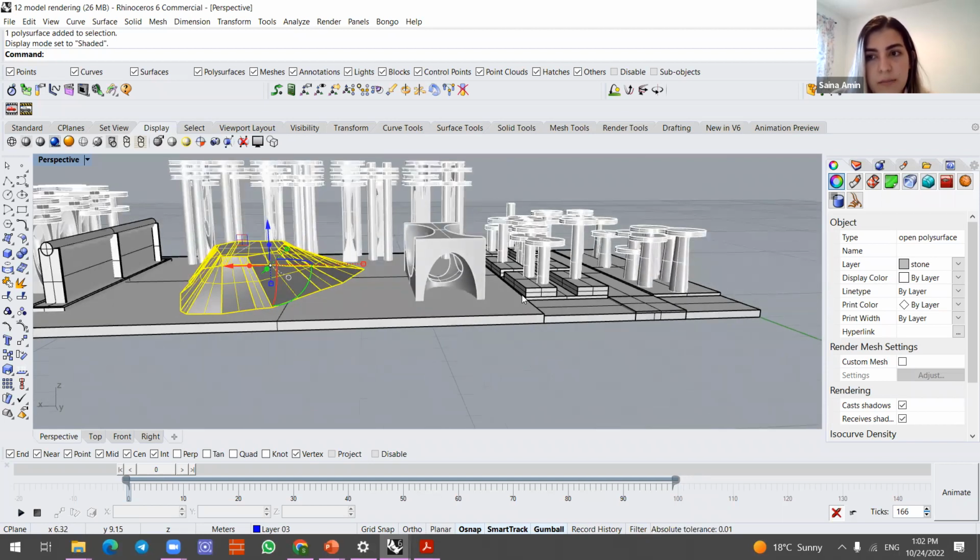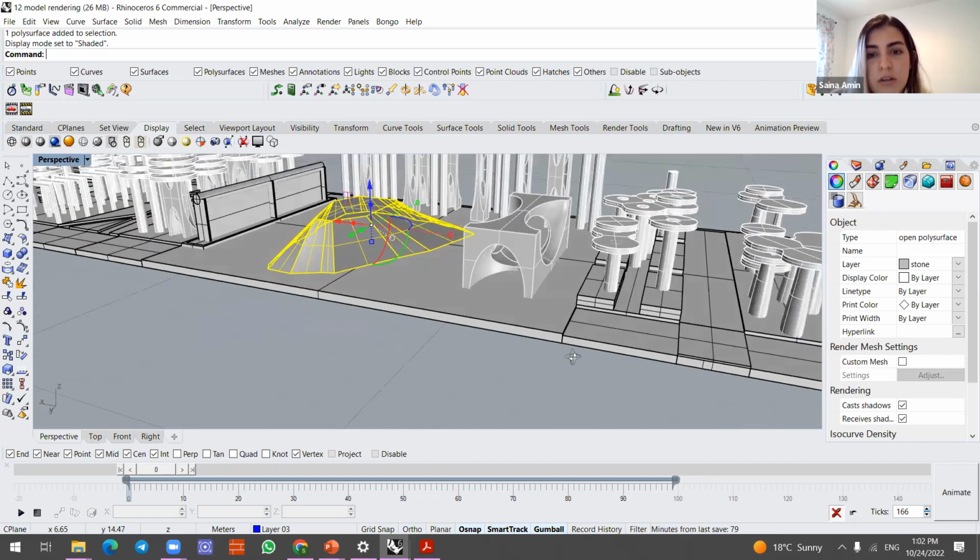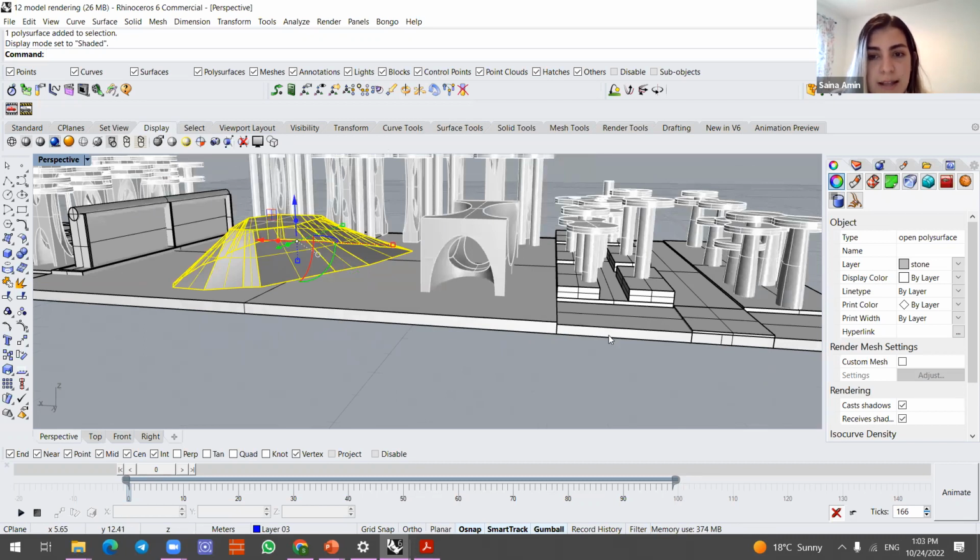But we should keep in our mind the 0.05 inches, that is the minimum thickness. We shouldn't go less than that one. And keep in mind that the 3D printer puts a typical and default surface under your foundation. So no worries about the foundation breaking or anything. Even if you don't choose anything as a foundation, it has some with your modeling. So try to keep it simple and as thick as you can.